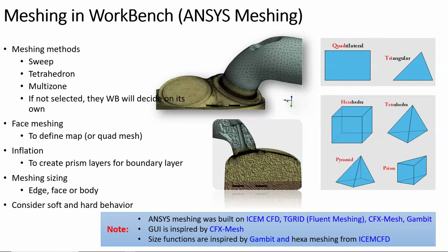So you can see here: 1, 2, 3, 4, 5, 6, 7, and 8. So 8 means that we have 8 vertices. This is only for the hexahedron. For tetrahedron, there will be 4 nodes, okay, on the corners. So the element will then be written as tetra 4. For triangle, this will be written as tri 3. It means this is a 2-dimensional element, and tetra 4 is a 3-dimensional element. And pyramid will be having 5 points or vertices, and prism will be having 6 vertices.